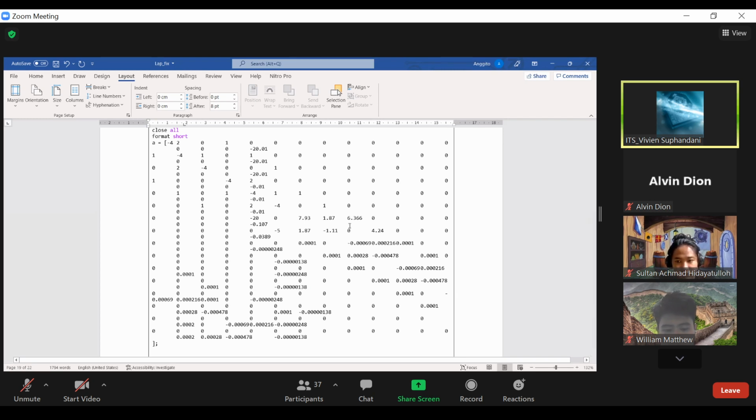As we have learned before, if the values have a very large difference in the order of magnitude, that will result in a very large round-off error. In this case, you have a diverged solution because of the round-off error. So if you have a very different order of magnitude, you can do scaling.